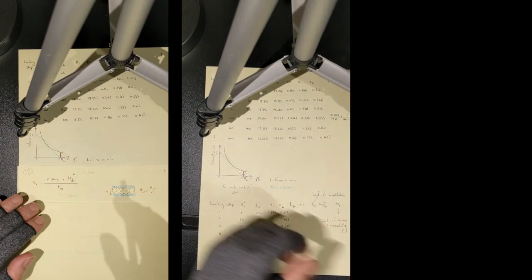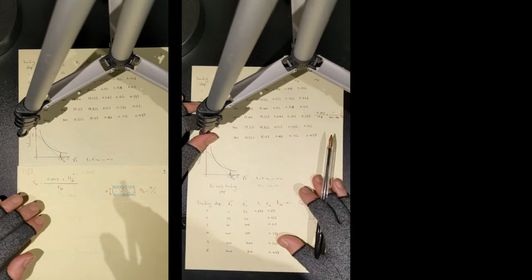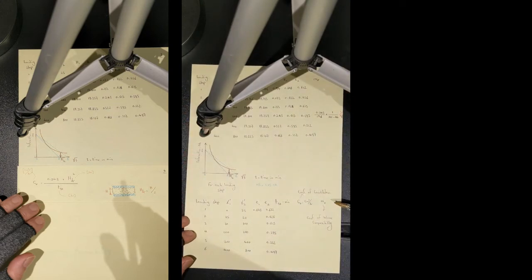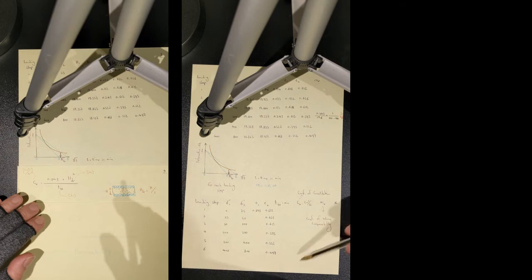There is one other useful parameter that you can determine for each loading step, and that is K. Do you remember K? K is permeability, coefficient of permeability. Probably you remember when I was teaching the permeability lecture, I taught you the constant head permeameter, and I said that it is a device that we use to measure the permeability of coarse-grained soils.